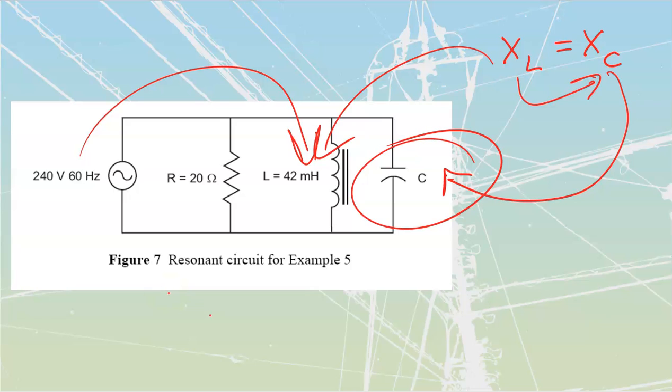There will be, once again, an inrush. When the circuit is first energized, there has to be extra current that's just going to flow for a split second just to fill the plates, based upon the size of the capacitor. But after that, those electrons that fill the plates are just going to be passing back and forth from inductor to capacitor, and they're just having a good time over here at this end of the circuit, while the rest of our circuit is doing true, useful work creating heat through this resistance that we have over here.